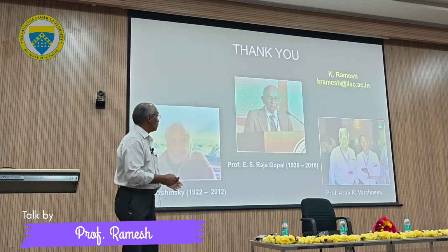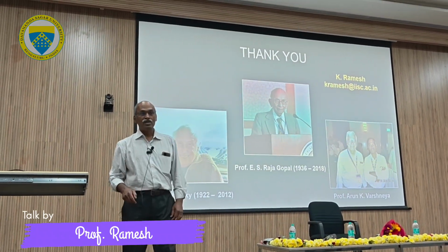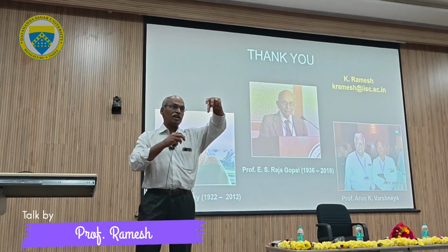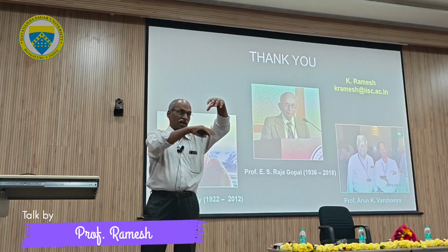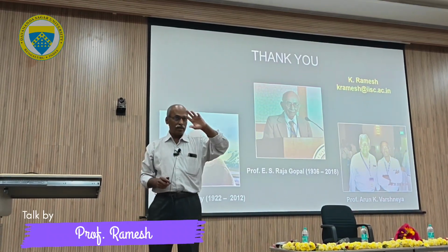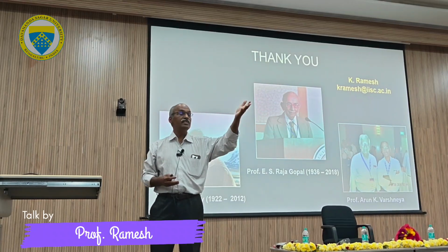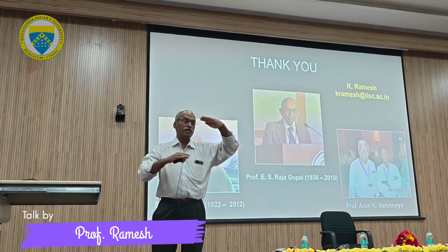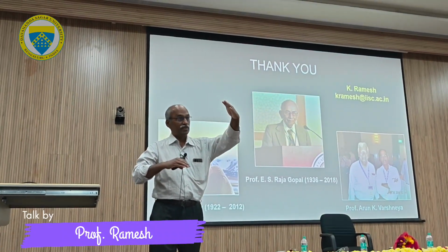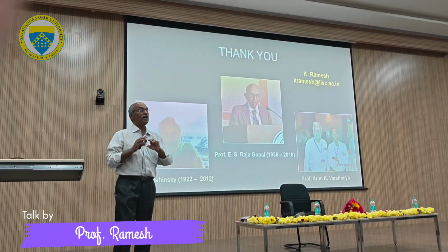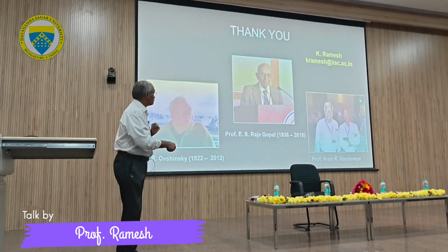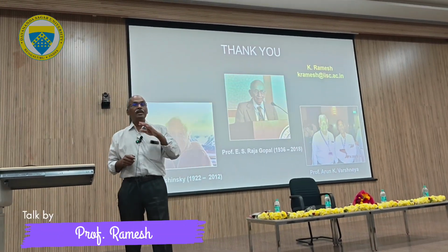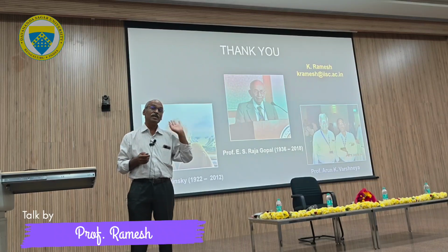So he made a way to strengthen these glasses, through ion exchange. These are soda lime silicate glasses. Sodium is a smaller atom, and potassium in the same group is a bigger atom. In materials, compressive strength is higher, about 10 times higher than tensile strength. So if a material is under compressive stress, its strength will be more. By ion exchange, replacing sodium with potassium, he strengthened these glasses, and saved millions and millions of lives.